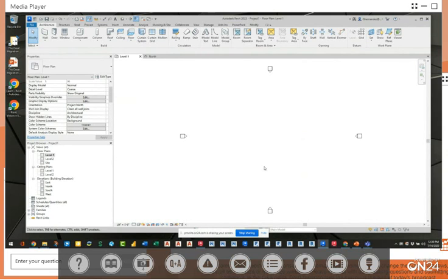Now, back here to my level 1 view, to start this project, all I really have to do is go into my tools now and start to draw in my design or my layouts. You can start with the actual floor first, or the structural slabs, and we'll talk about the difference between an architectural floor and a structural floor in a second. They're very similar. They're the same, except that structural will actually show up in a structural model where architectural won't.